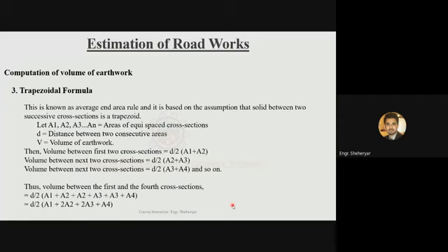Then comes the trapezoidal formula. So let's see how it works. This formula is assuming that the road segment between two chainages is a trapezium, or is like a trapezoid.